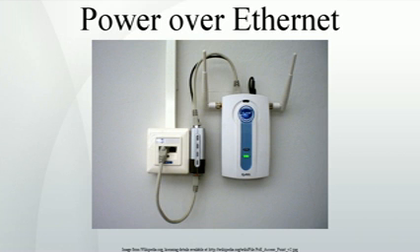IEEE 1394, FireWire, is similar to USB but can provide substantially more power, 45 W, at a distance of 4.5 m. If a device already has power available but no data link, then PoE may not be attractive. A wireless data connection such as IEEE 802.11 may be more economical than running a data cable for the device. Alternatively, there are power line communication technologies that can use power cables for transmitting data. Using some power line modems may be more economical than running a cable.